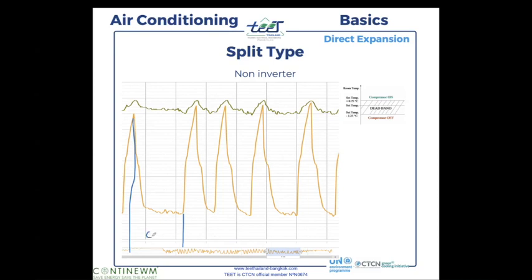So this means exactly during this time, until here, you can say that the compressor is on, okay? So when the compressor is on, remember the refrigeration cycle, we put pressure on the refrigerant fluid. So there is a lot of pressure. So the expansion is very powerful. So it's getting cold, okay? You extract the heat, the heat exchange that I explained. All of this makes sense now just with this line, okay? Because you can see, we start to get high pressure refrigerant fluid that is expanded, the temperature drops, okay?